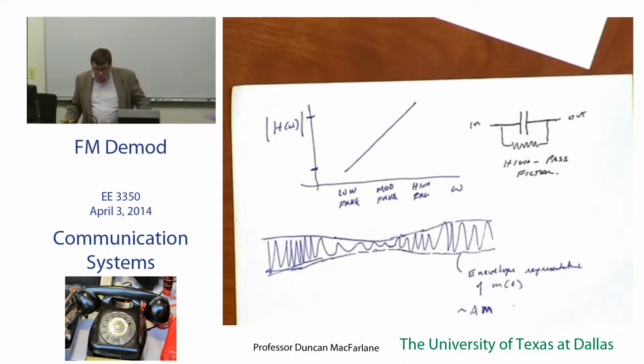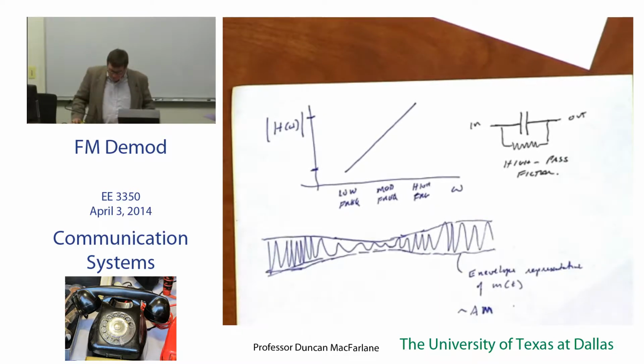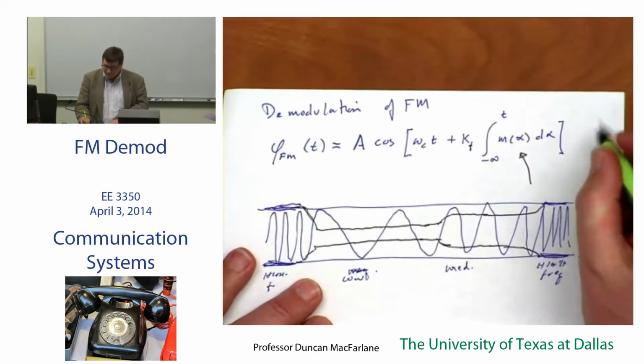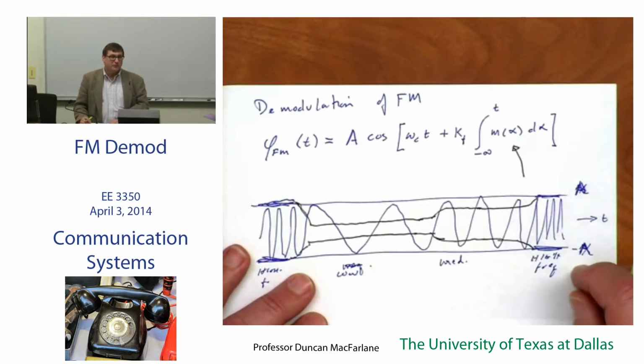Now, this high pass filter is also a differentiator. Right? A high pass filter is a differentiator. A low pass filter is an integrator or an averager. I've tried to go over that about 1 million times, and the reason I've tried to go over that 1 million times and to get you guys to buy into it is for exactly this moment in our lectures. Okay? Because now what I can do is I can analyze the effect of this filter on this signal here much more precisely and much more nicely.